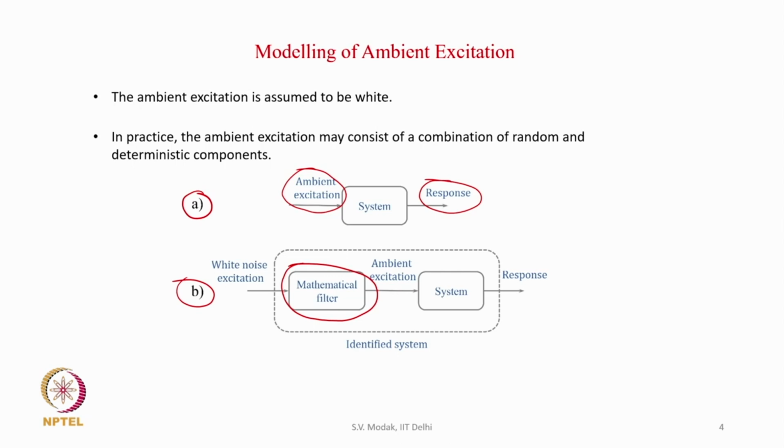So, therefore, when the operational modal analysis analyzes this response, it effectively identifies the model parameters of the combined system. You can see this is the combined system, represented here as the identified system. This dotted rectangular block represents the combination of the mathematical filter and the actual system.